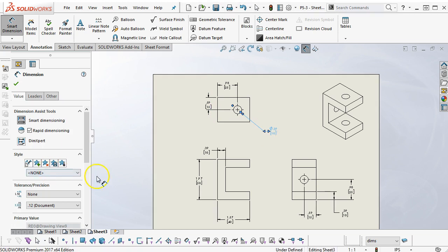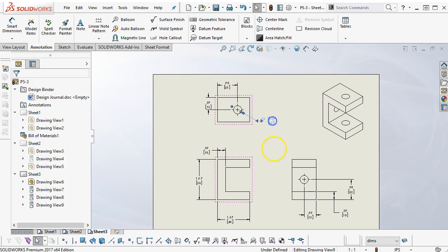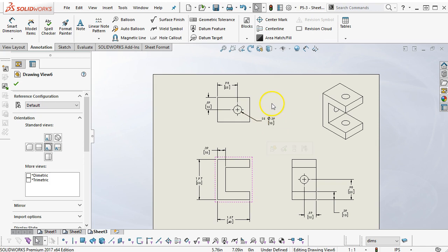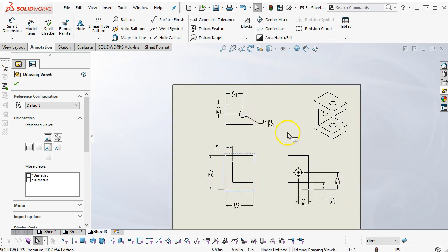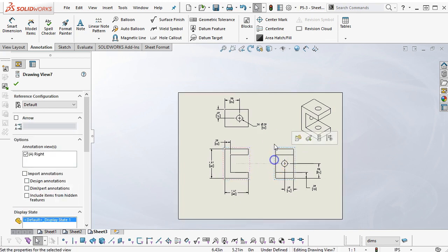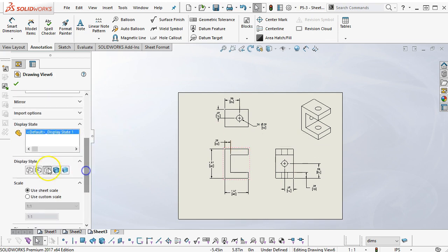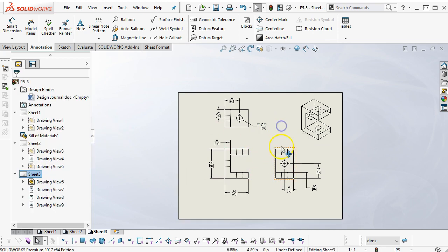Okay, and then we'll go, if we don't go to the box, then we'll come over to the dimension text 3 times and accept. All right, so since the view, my general process for hidden lines is that if it adds something to the view and doesn't make them more distracting, then we'll go ahead and put those in place.